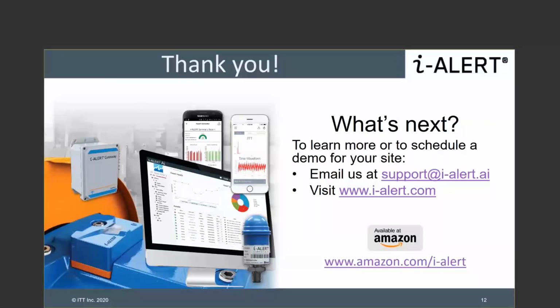So once you have all the assets in your plant categorized, then you would attack the lowest hanging fruit first and start putting monitoring on those pieces of equipment that are giving you the most trouble and are most critical to the operation of the plant. I would say lastly, you would want to look at all the other plant equipment, so-called balance of plant type equipment.